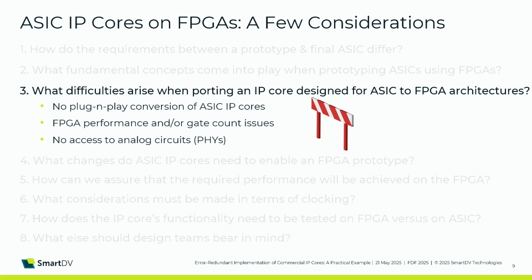Quite a few IP cores require not only the digital part, obviously, but also the external PHY. Okay, in an ASIC, it's not an issue. You can use an analog function that can be put on the same die. But when it comes to the FPGA implementation, you will need an external PHY component, and you must make sure that this PHY component will work seamlessly with the digital IP.